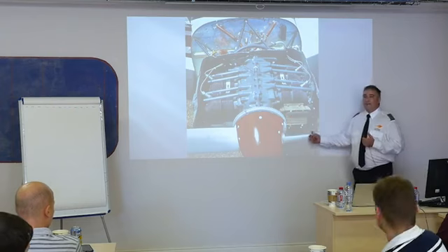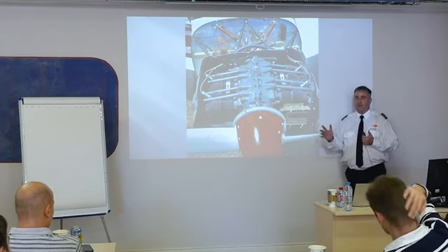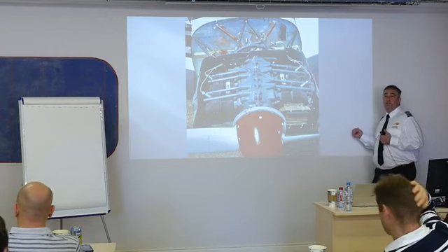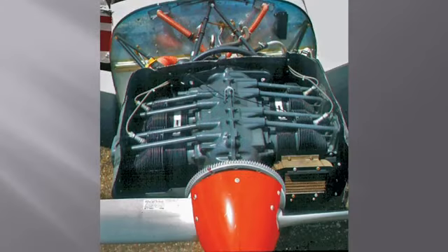If it went any faster than 2,800, 3,000 RPM, you would have serious separation at the tips because it exceeded the local speed of sound. So there is a maximum amount of revolutions per minute for this propeller. If the engine turns in excess of that RPM, then it has to be reduced through gears.